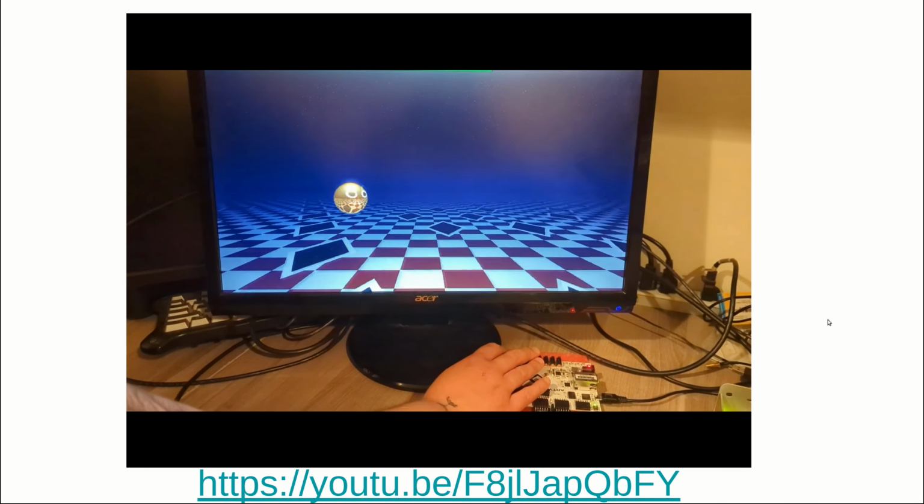There's 2 clock domains, so essentially 2 pragma main functions that you're dealing with. One here on the left, frame logic. That's stuff on each frame, so this is 60 frames a second, 60 hertz, and what it ends up being is just a really slow state machine. You're saying, position of the sphere at this frame, the next frame is some computation, and that determines the position. If the button's being pressed, change the direction that the sphere is traveling in when it hits the floor, kind of logic, and no problem meeting timing in there at 60 hertz.